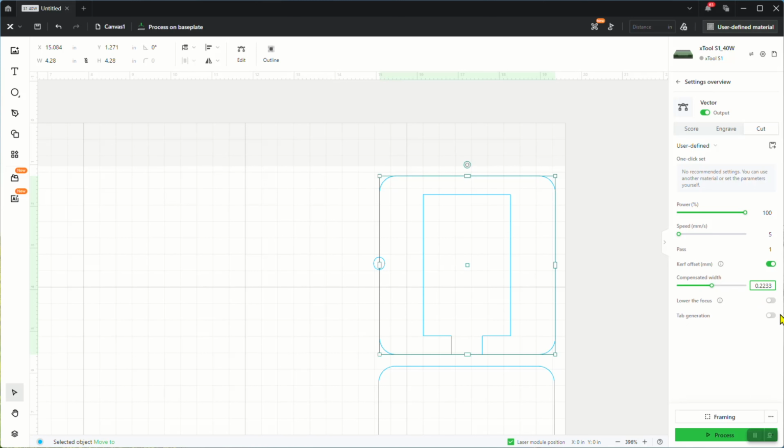You can put as many 3s in as you want, but it's always going to only come back to 2 decimals. I don't know why. I mean, it's a laser. It should be able to be more specific than that. The CNC machines that I use, they go down to 4 and 5 digits. If you need this to be someplace between 0.22 and 0.23, you're going to have to convert all this stuff to millimeters.